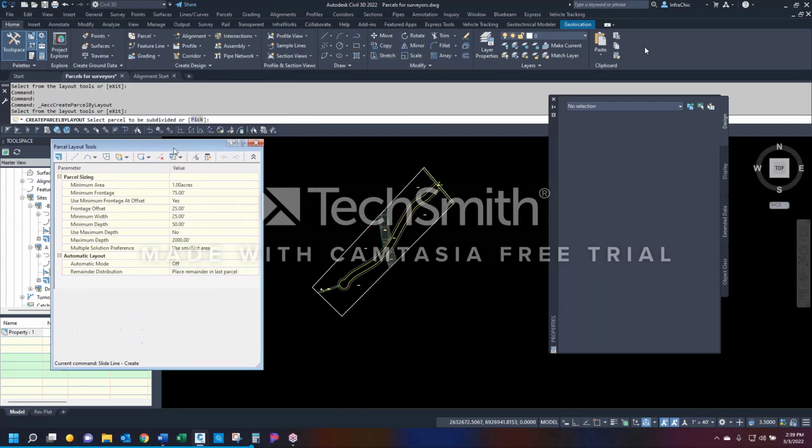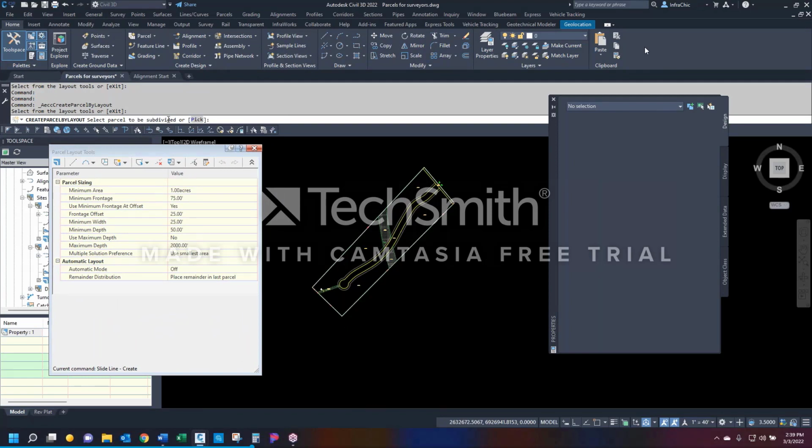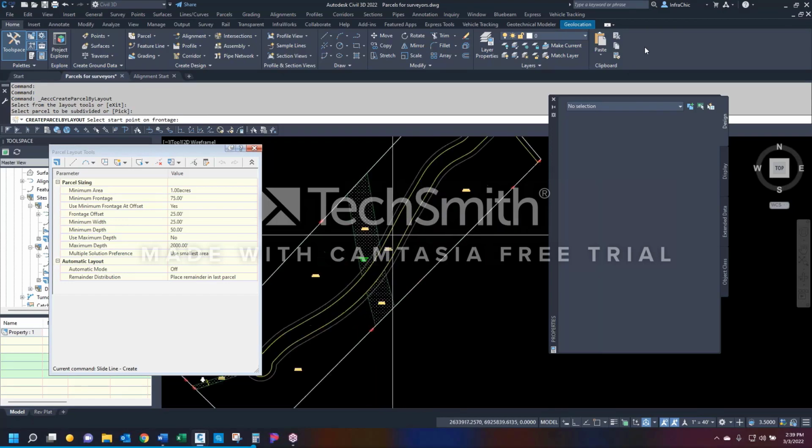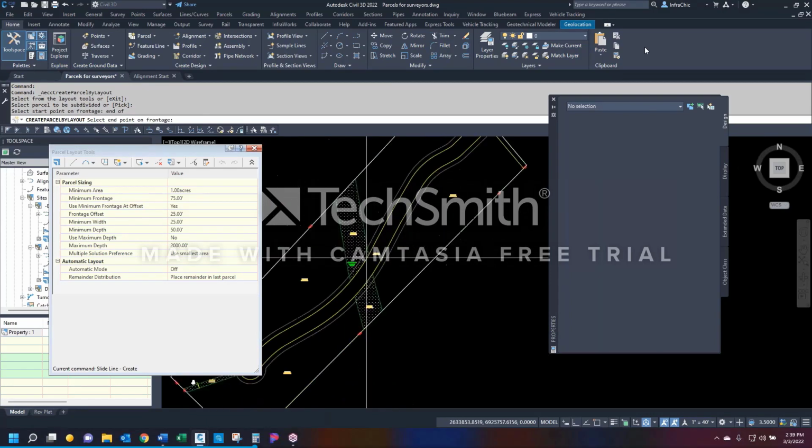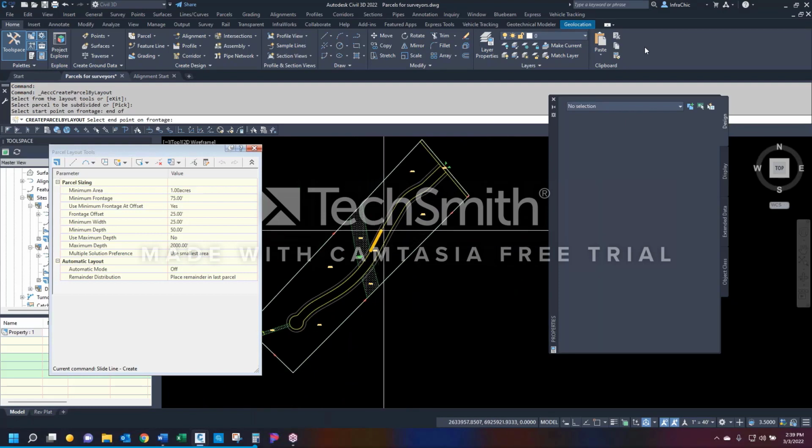Now, I'm going to move this out of the way. Select the parcel to be subdivided or pick. So it means select the parcel area label, not the line work, the label. We'll start at the front. Okay, it said it found it. Now, select a starting point on the frontage. The frontage is this line, the yellow roadway boundary line. And I'm going to choose end, typing in end, enter, grabbing a point.